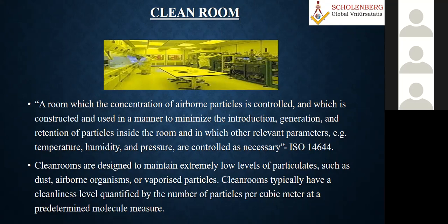Basically, it's a room or any area in which the concentration of airborne particles is controlled. In any closed area, the air has to be treated properly, so when airborne particles are there, that is to be controlled. It is constructed and used in a manner to minimize the introduction, generation, again from the source, and retention of particles inside the room, and in which other relevant parameters, for example temperature, humidity, and pressure, are controlled as necessary. That room is called a clean room.